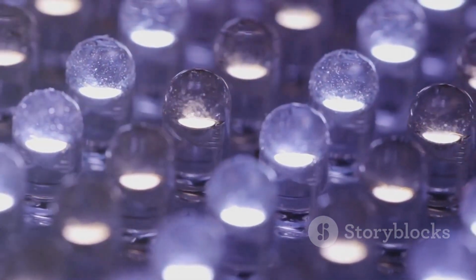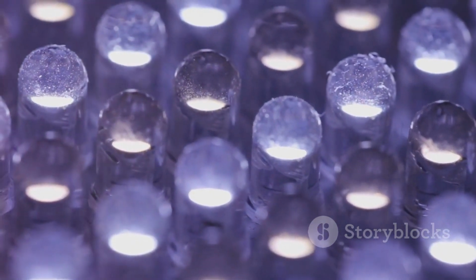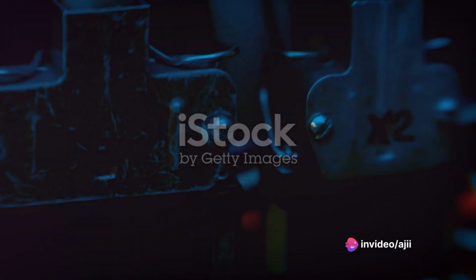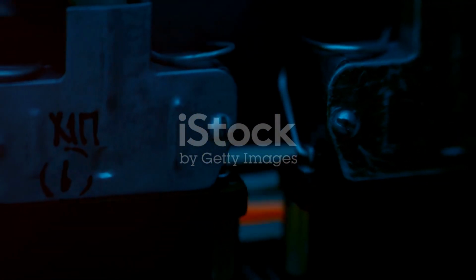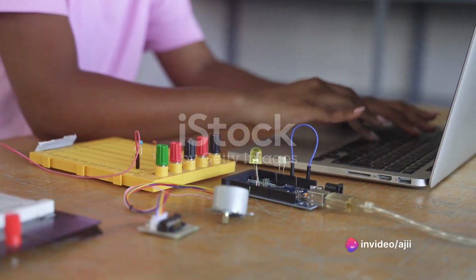In this setup, we have an LED, which stands for light-emitting diode, and our main component of interest, the diode, connected in series. For this experiment, I've connected the cathode of the diode towards the positive side of our power supply. Remember, the cathode is the side of the diode with the line, according to the symbol we discussed earlier. Now, let's see what happens when we apply a voltage across this circuit.